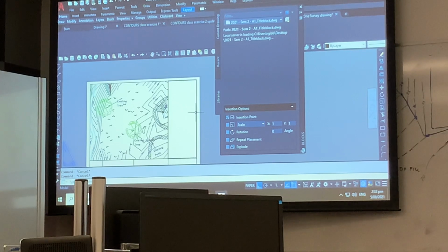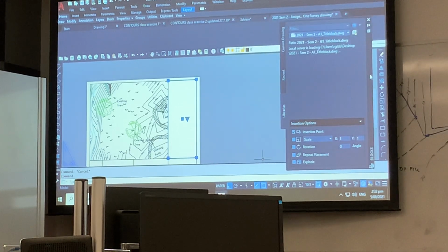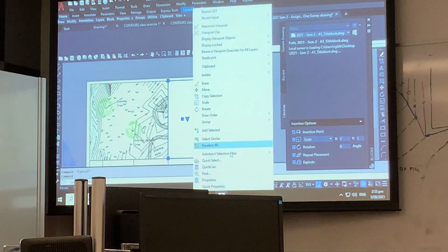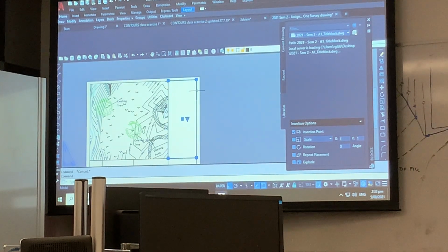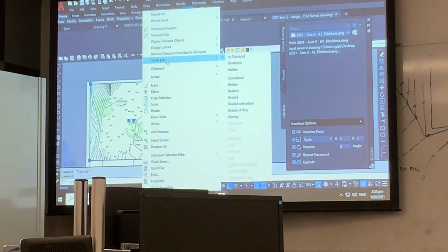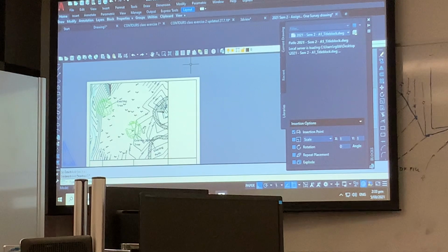So let's click on here, and there you see the number 10 along the bottom. That's a rounded number. So always check your viewport before you check the 10, all right? And once you've got it correct, lock it up. Right click on it, and if you're happy with it, go to display lock and go yes, and you can never lose one mark now from Roger. It's a really good tip, that one. Display lock, yes. Ha, Roger, you're never going to get me half a mark off, right?